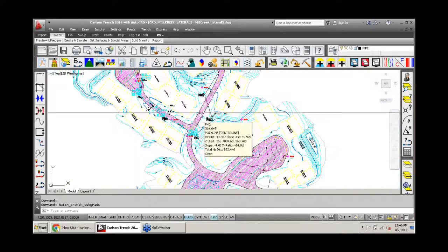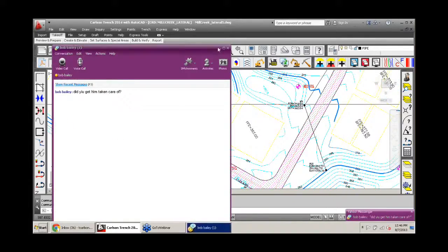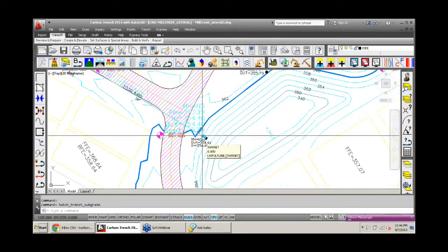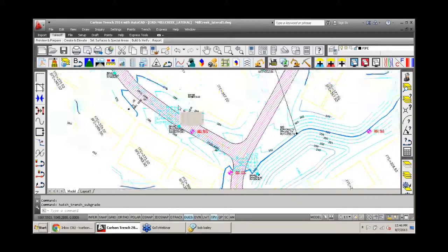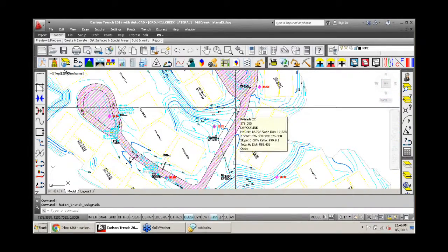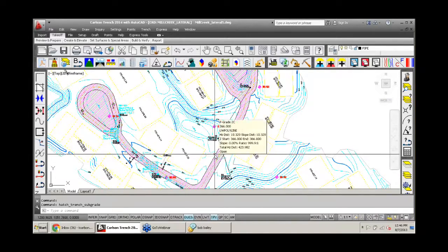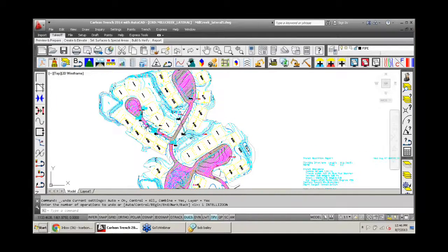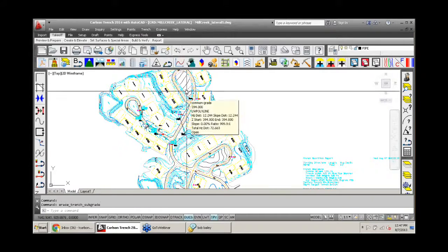okay, I can see for my trench, where is it going to use that subgrade, and where is it going to use the main template. So most of this looks like it's inside of my road. When we enter this one in manually, I'll have more of the main template. But when it's crossing the road, it's going to use those different backfill quantities that I defined. So I'm going to go to trench and just erase that hatching.